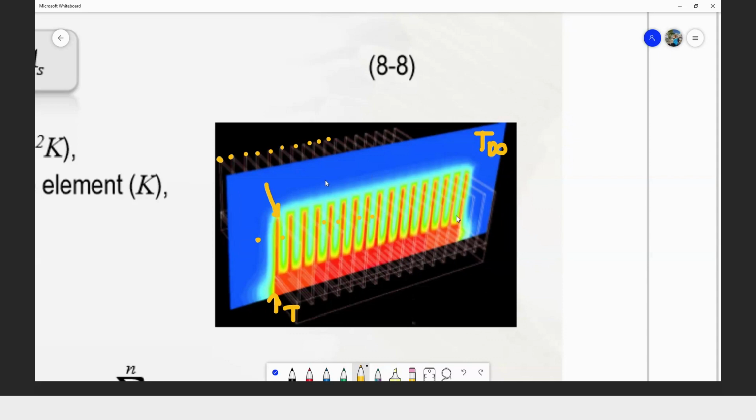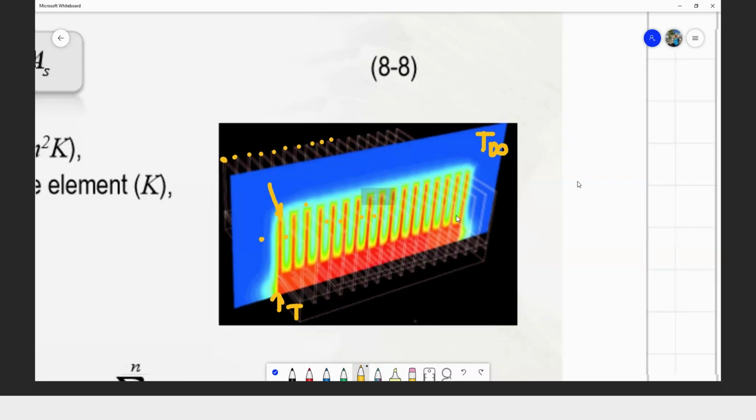So actually, it's not necessarily the same temperature at both sides of the fins. The closer the arrangement, the closer the temperature between the surrounding fins, the middle fins, except the ones at the very edge. If the gap is bigger, between one fin here and the next fin there, the temperature gradient may be higher, so it may not be the same.